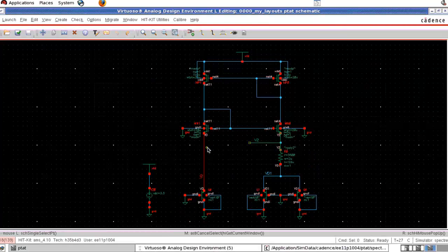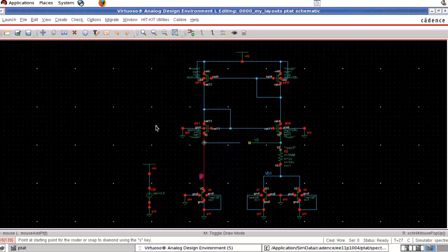That means this voltage and this voltage are very close. So if you want VD exactly equal to V2, you have to improve your current mirror. You can have cascode current mirror and other more complicated improved current mirror structures for that.